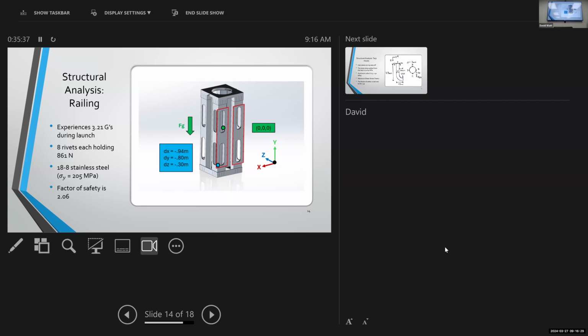So 1,000 divided by 750 is going to give me what, like 1 1/3, right? And I'm going to subtract 1 from that. So my margin of safety is positive 0.33, positive 33%, right? My structure is 33% stronger than it needs to be to carry the loads with the factor of safety that it's going to see in service. So essentially, this is what's allowable. This is what it's predicted to be loaded with. Here's the target factor of safety. How much quote unquote extra do we have?